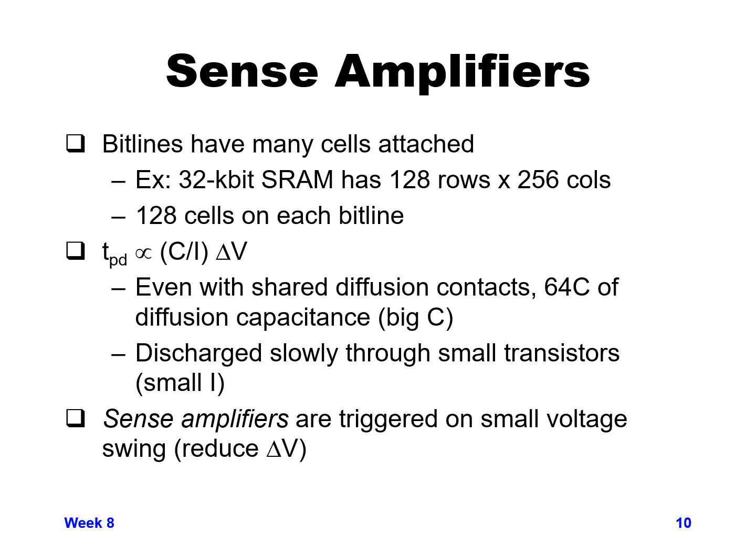What we wind up using is a sense amplifier to detect the difference between bit and bit bar, and we can figure out which one has been pulled down, even though it hasn't been pulled down far enough to cause an inverter to switch. With a differential sense amplifier between bit and bit bar, we can detect which side has been pulled down, and which side is supposed to be 0 and which side is supposed to be 1.